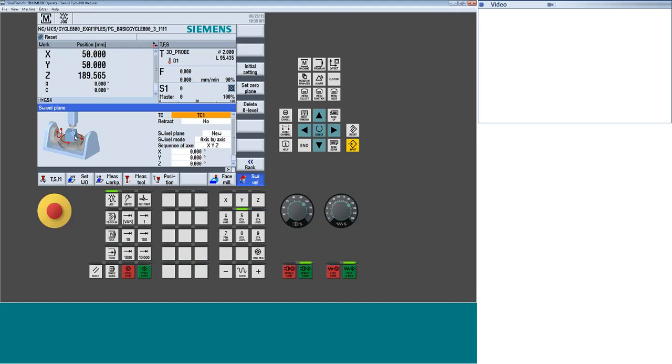So it's going to know where is my center line of A in relation to the platter of C, and where is the distance between the center of C in relation to the center line of A, if there's any discrepancy there. So if the part swings up and there is a discrepancy and everything's not perfect, which there never is, the system will automatically track and compensate for that.